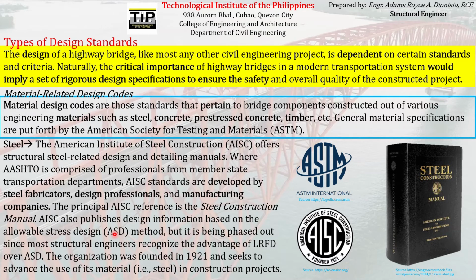Nowadays the ASD method is usually being phased out because there is an advantage of using LRFD over ASD. So nowadays we are more inclined to use the LRFD method instead of ASD.